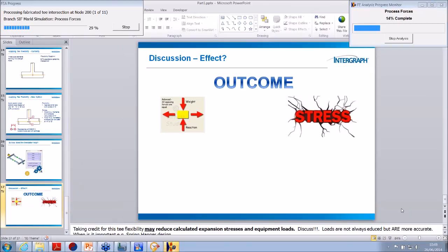The main problem is that lateral around 180 and the branch around 2110. They were the ones which failed in the sustained load case. And on the expansion case, on the main large header, there's a number of laterals, and each one of these is currently rigid, so there's no flexibility. And this is why we have all these failures, as I explained when we were searching through the model.